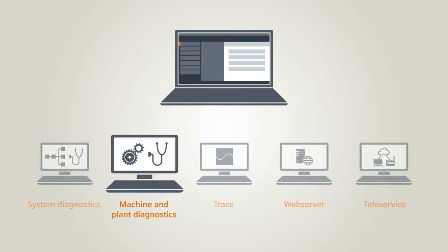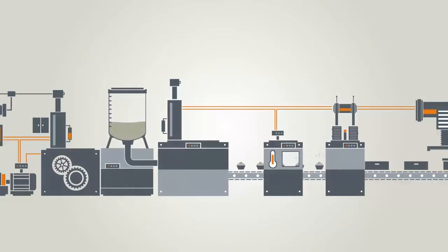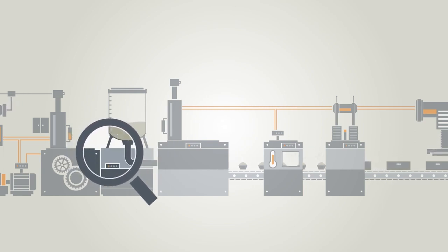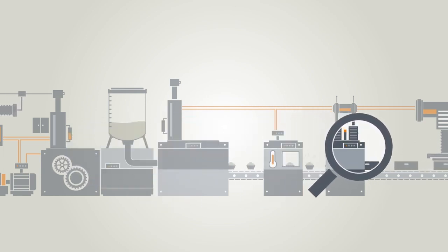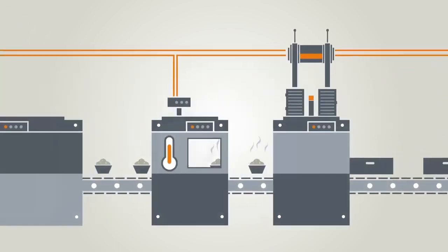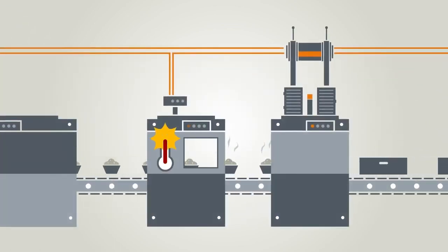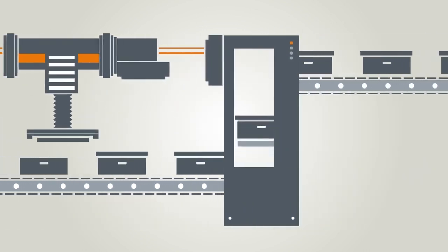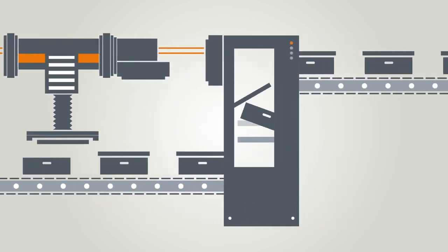With the process diagnostics ProDiag integrated in the TIA portal, you can individually configure the monitoring of process variables for your plant and thus troubleshoot faults while the system is running. For example, if a temperature is exceeded, or if a lifting unit no longer reaches its limit position.